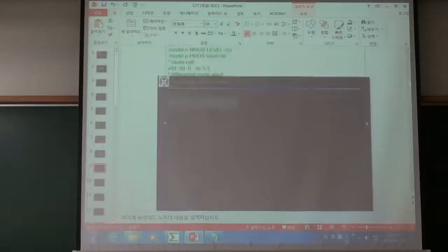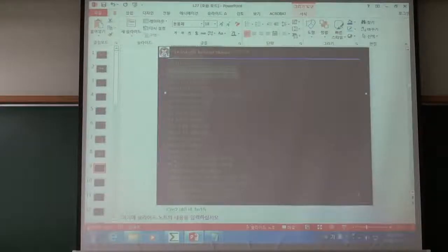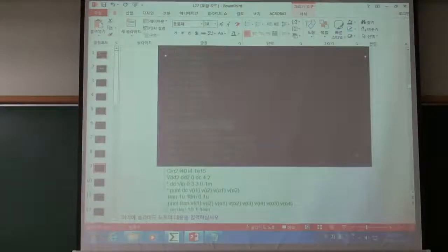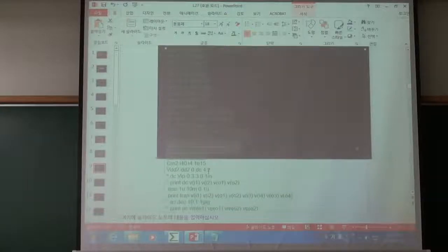And for this X8, I3, I4, I will apply common mode input, okay? Here, through capacitor. So in O3, O4, I will have a common mode output. O1 and O2, I will have a differential mode output, right? Okay? And then I will change this VDD2. So this time, this is 4.2, or too large, maybe. Okay, let's just simulate this one.